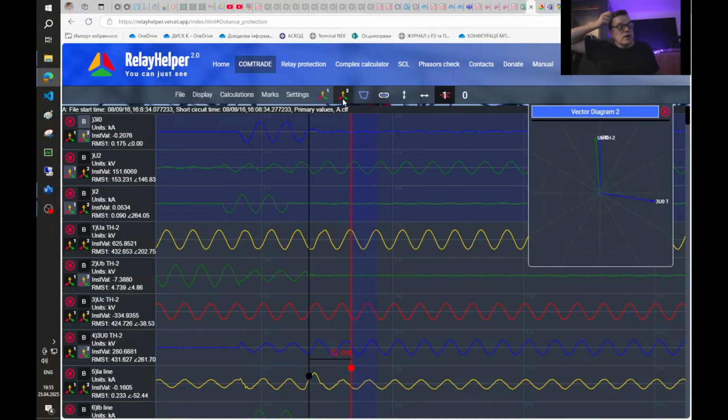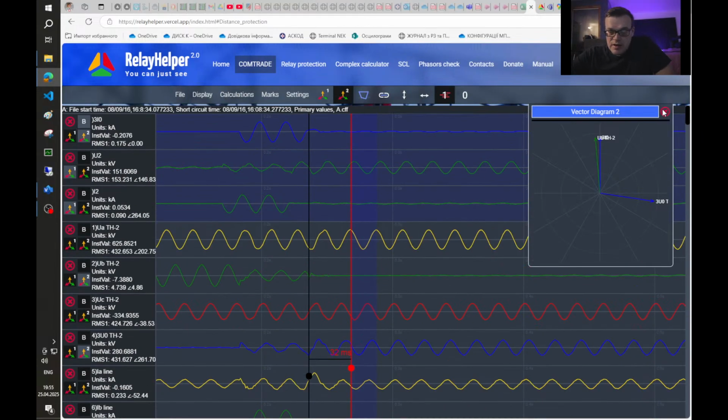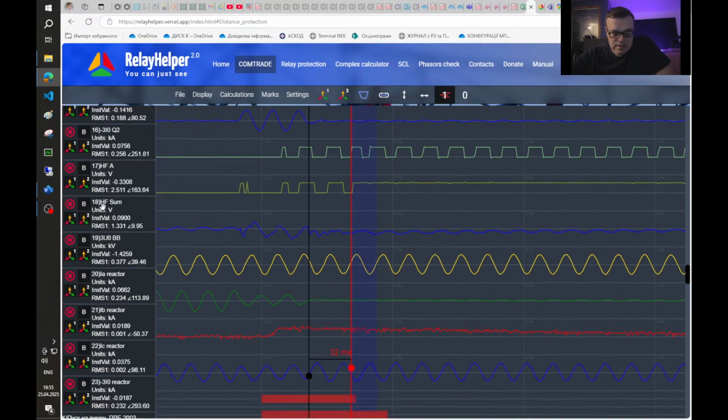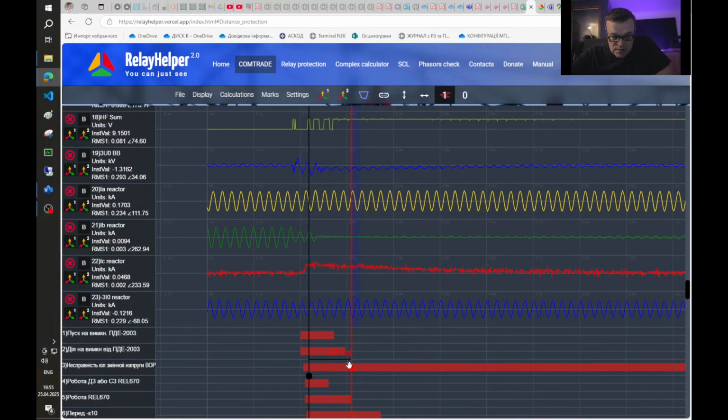And we also have one more way to determine the period of time when the arc went out. This can be done through the zero sequence current of the shunt reactor. During this single phase trip, this zero sequence current has a DC component.